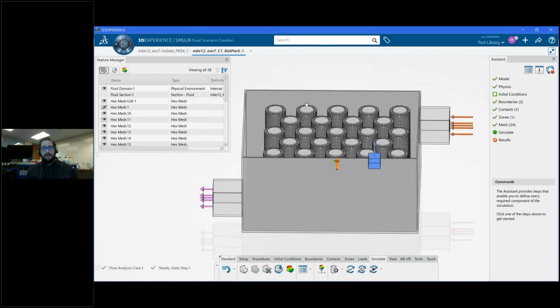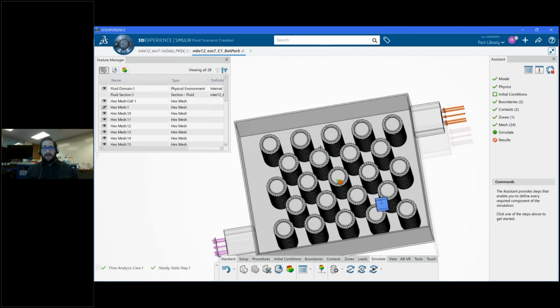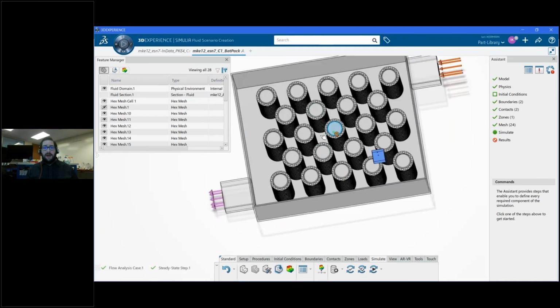And what I'm going to simulate is a short circuit on this cell here. So the idea is that if something happens to this cell and it short circuits, it's going to discharge all of its energy very quickly as heat. And I want to see first, how is that heat dissipated in the system? And also, does this cause damage to any of the neighboring cells?